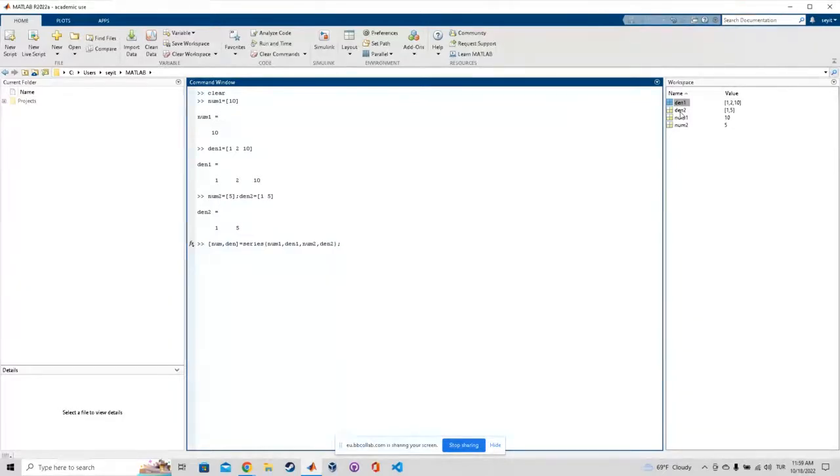And then let's say, we want to print our system. You just write print system, right? And then open parentheses. In the parentheses, you should write just numerator and denominator again, right? We had two systems, system 1 and system 2, and then we add these two systems in series together, and we get our transfer function, numerator over denominator. All right, this is okay, guys. Till here, how we add series systems together.